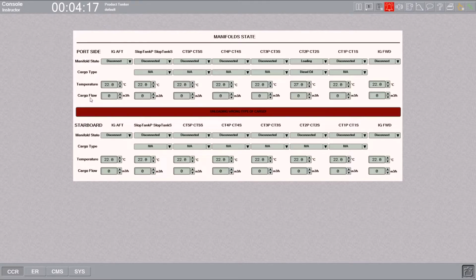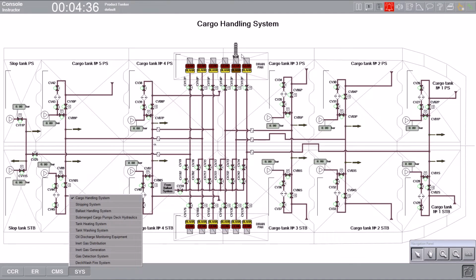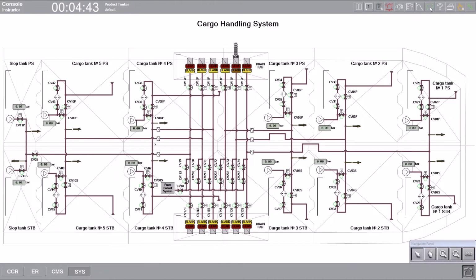And the loading rate, you have to request from the terminal: please provide me the loading rate. Initial loading rate we will take 100 cubic meters per hour. So we just mention no more than 100 cubic meters per hour loading diesel oil. Return back to the system and check. Here are the tips. To see the running cargo, we must switch on these tips.